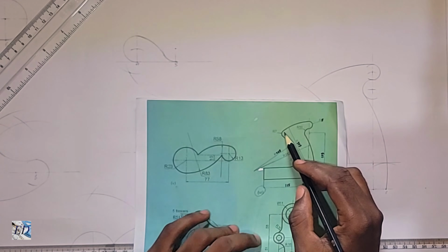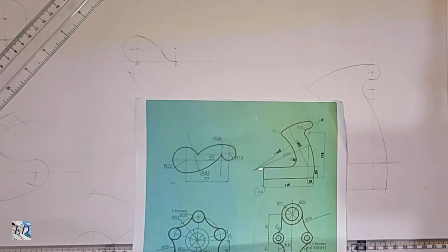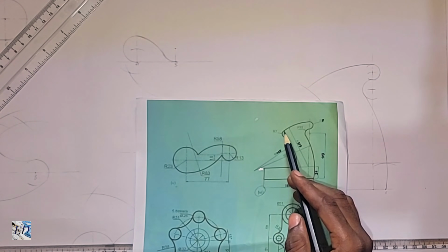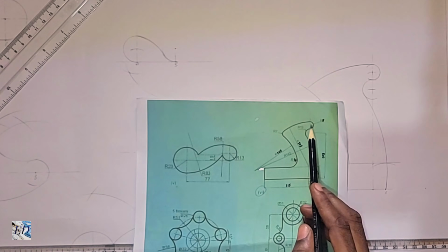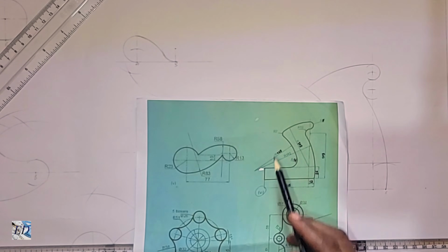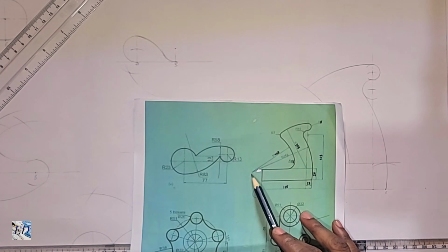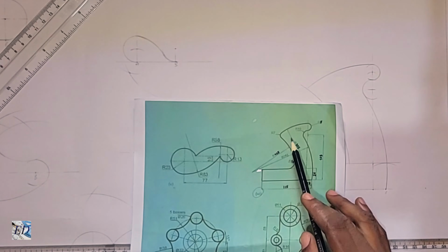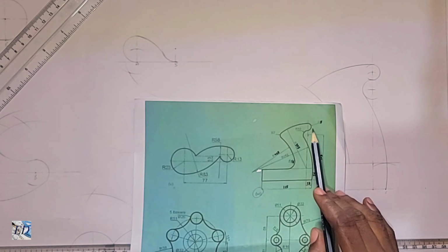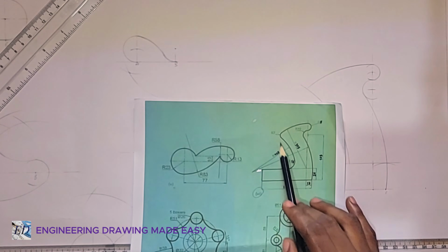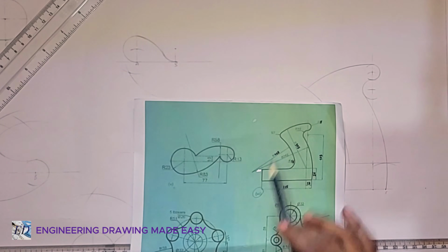Now, working on this part of the circle is fairly easy compared to what I've been doing so far in today's video. We have a circle here that is touching this particular arc internally and then touching this particular arc externally. So from here you add the radius of 7 to this and try to find the center, and then you subtract 7 from this and try to find the center.